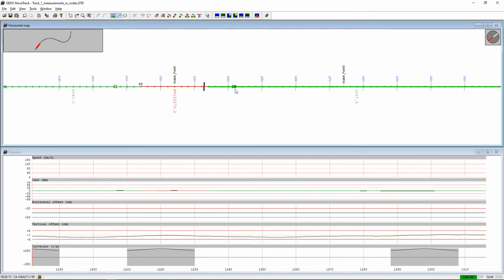Each straight element has 2 control points. As you can see, the beginning of the straight element has a cross, and the end control point of the straight element has a circle. In the next step, if I want to lock these 2 straight elements exactly at the switch point 1, we have to move the control points exactly over the switch point 1.